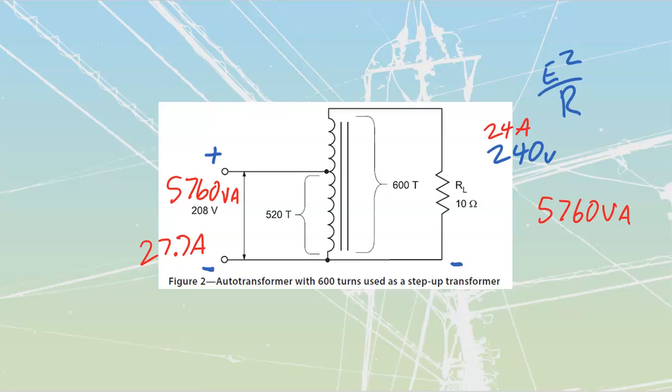So we can start by establishing directions of current based on those two facts. We know that we are going to have current entering into the transformer and traveling up and through, right? It has to go through a load from negative to the more positive end of the load. So I must have 24 amps entering in here, driving through there, and then coming back down over here. That's going to be 24 amps over there. This is going to be 24 amps over here.